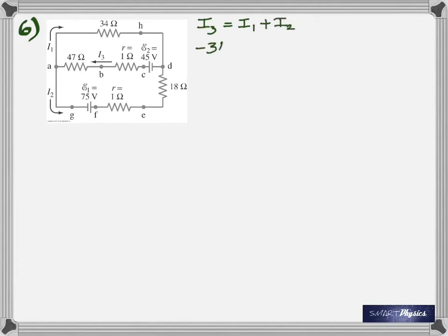And then when you try to apply Kirchhoff's voltage law, in the top mesh, going around in the clockwise direction, let's say you start from here and the current flowing is I1. Since you're going in the direction of the current, it's negative 34 I1. Then as you come here, you are going from the negative to the positive of the battery, so it's plus 45.